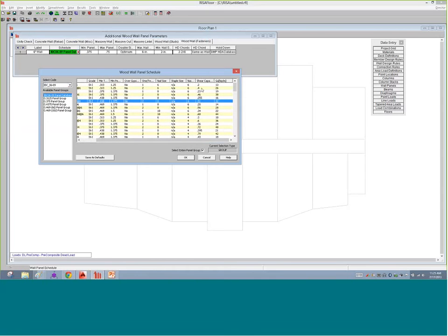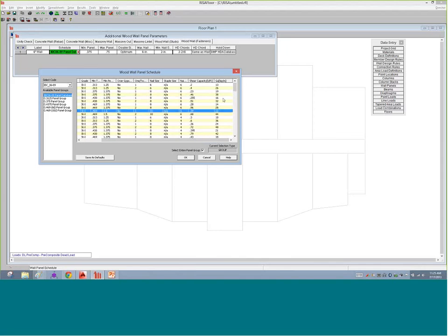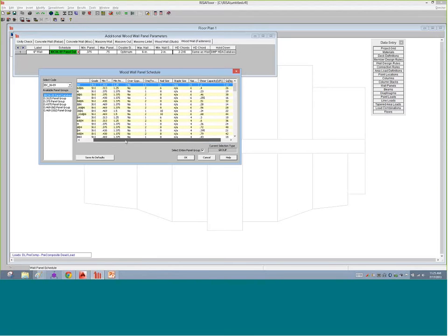You can see the shear capacity is listed at the end of that number. That's really the hot number that I care about. The GA also gives us information for the deflection, but we can see here we've got our shear capacity listed. It is the most important piece.